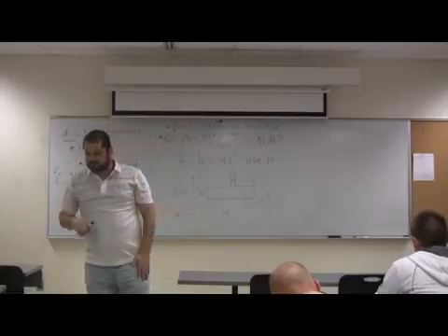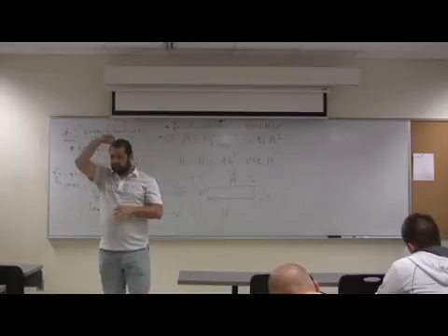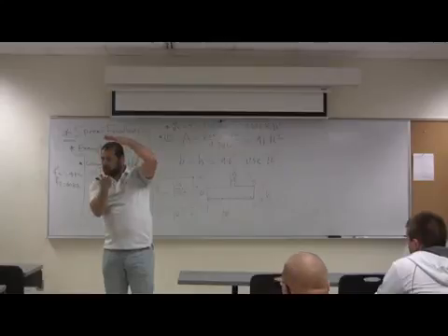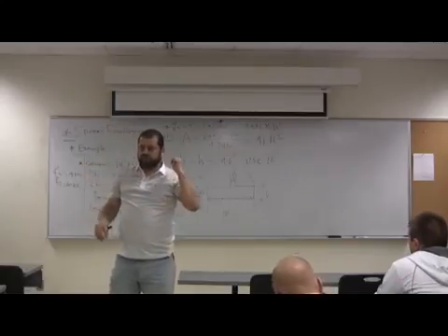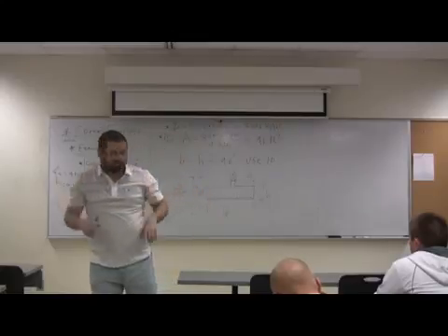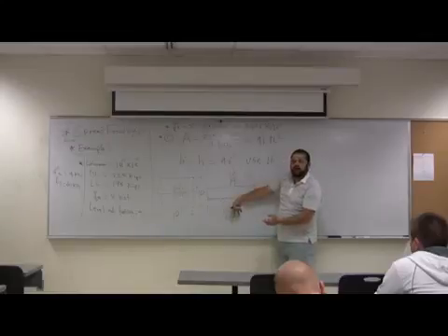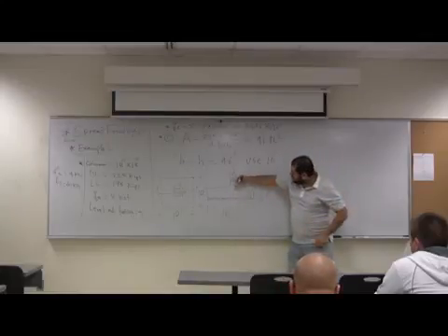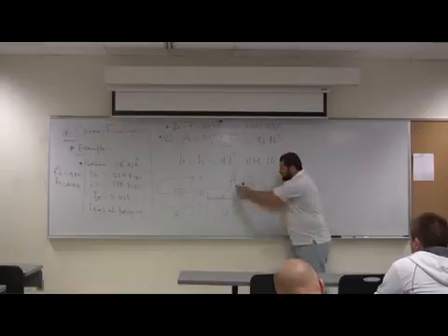There's something else. There's something called punching. Sometimes the column loads are high and the footing underneath is shallow or small thickness, the column may punch the footing or may cause cracking in the footing. So this one may, with this load, break it somehow. If it's going to punch it, you know what's going to happen? The cracks will develop at 45 degrees. They crack it like that.